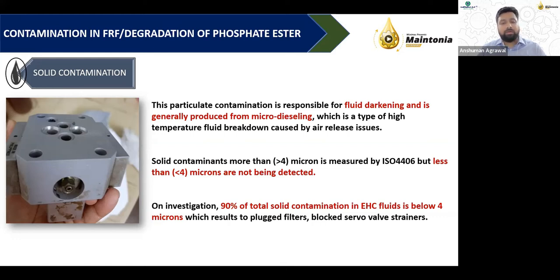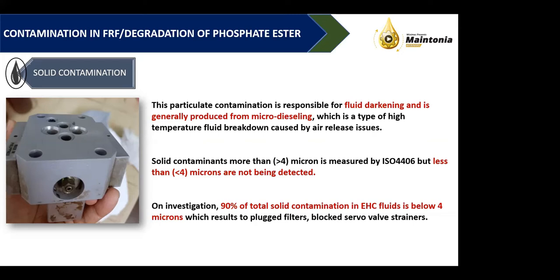I believe that's because there are a lot of fine particles in such systems. But I was just wondering, Mr. Yogesh, we already have that pencil filter, which is a one-pass filter in all the servo valves. Then what's the reason that these servo valves are failing? Because of contaminant? Yeah, just a few minutes back, I mentioned that this is not failure because of one big particle, but it is due to continuous settlement of the particles on the spool to form a thick layer over the corners.